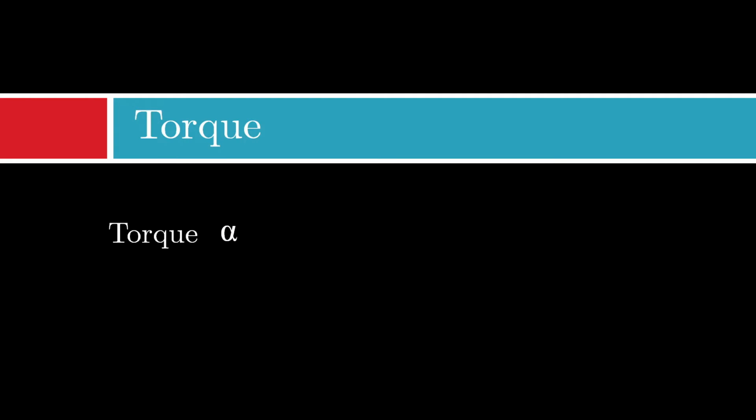So earlier we talked about this torque that is proportional to the two magnetic fields, then the sine value of the angle difference of these two fluxes. So here you can control this value of torque by controlling the magnitude of flux. You can control the angle between these two fluxes, and thereby you can easily control the torque.